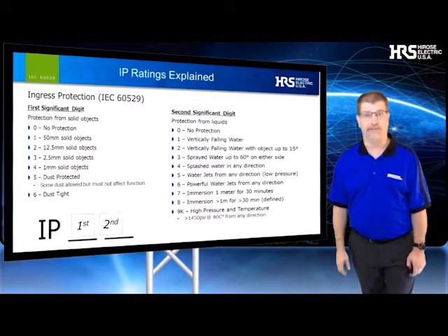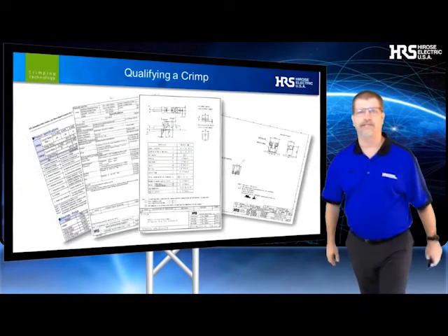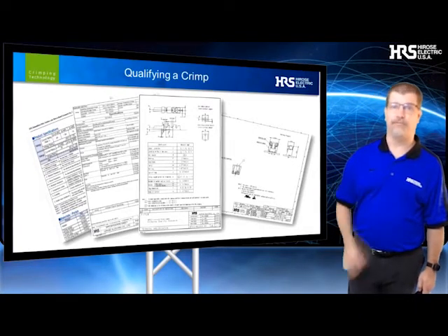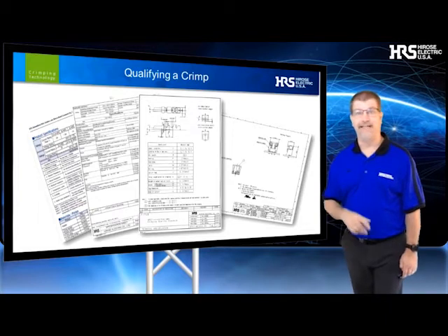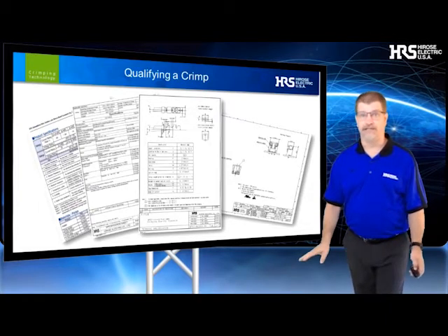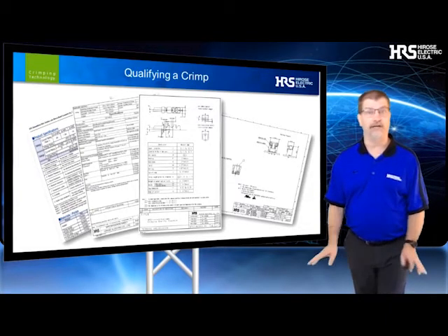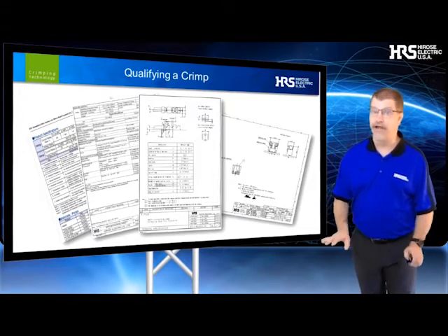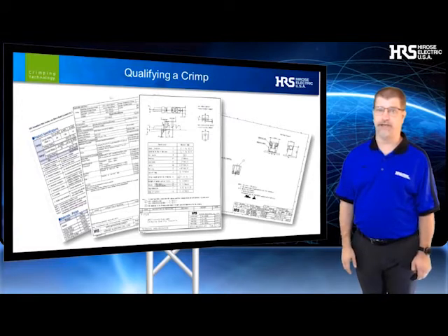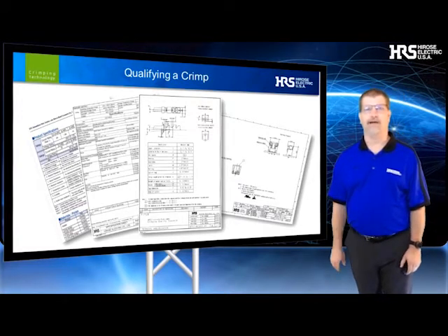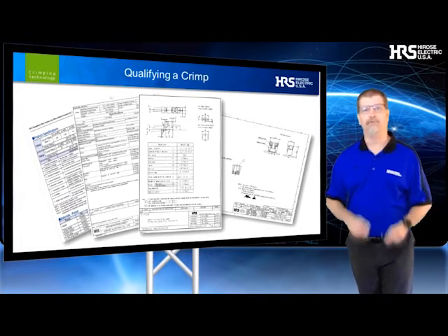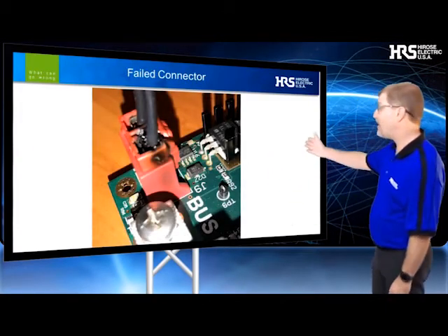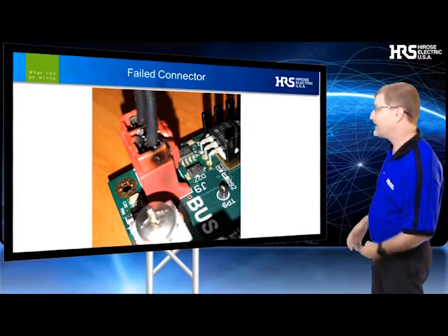With all that we have covered today, there is one last thing I want to mention about connector ratings before I move on to board-to-board power, and that is crimp quality. Regardless of the ratings listed on a datasheet or technical specification, if that crimp is not done right, the connector will not support the rated current that you expect. There is an amazing amount of technology in what seems to be a simple crimp connection.